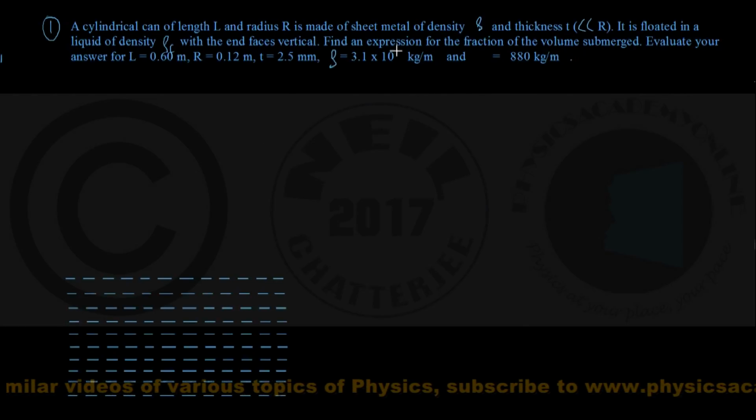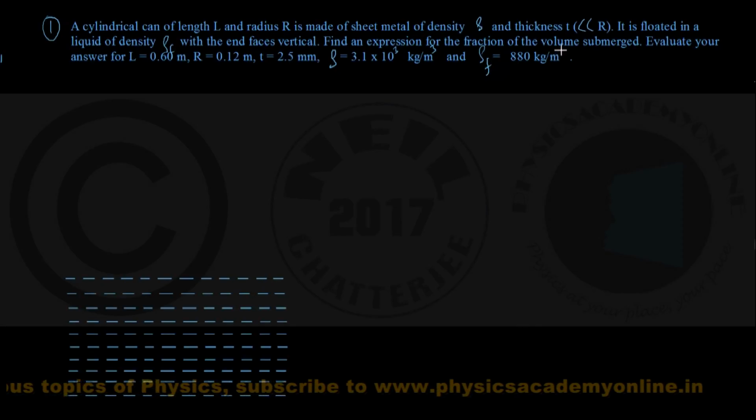See this part carefully, a slightly unusual way of floating, with the end faces vertical. Find an expression for the fraction of the volume submerged. Evaluate your answer for L equal to 0.60 meter, capital R 0.12 meter, T 2.5 millimeter, density rho of sheet metal 3.1 into 10 to the power 3 kg per meter cube, and density of the liquid rho F equal to 880 kg per meter cube.